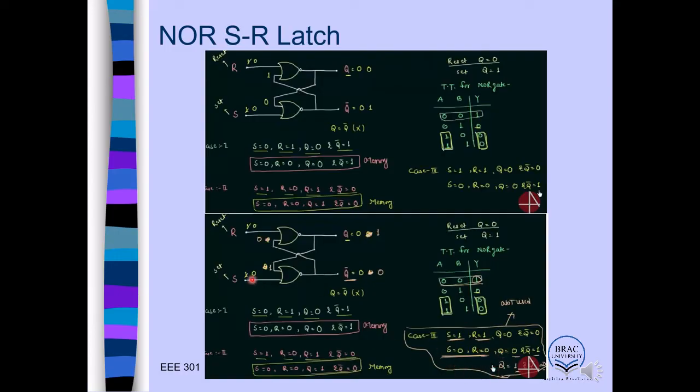If you start with this gate, we had R equals 0 and previously you have 0 here, Q 0. So these zeros go here, 0 0. So 0 0 becomes 1. So this output becomes 1. This one comes here, 1 0, so 1 0 becomes 0. Now your Q changes to 1 and 0. Previously it was 0 and 1, now it changes to 1 and 0.